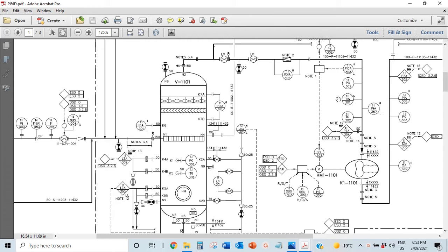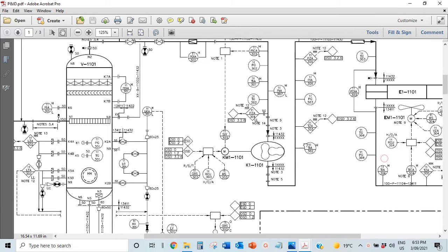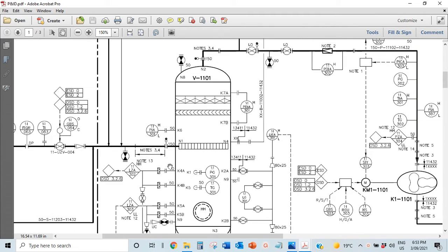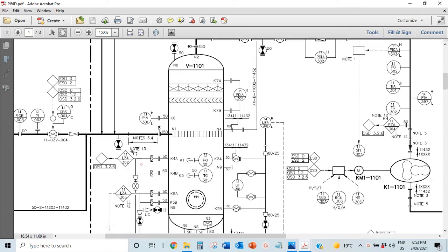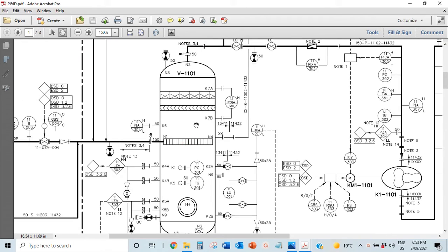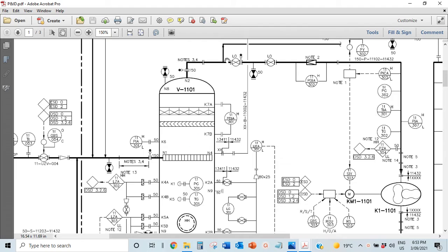So this is the kind of system you would use to do that. You would need a compressor and some fans. The gas comes in from here, and it's going to be mainly gas, though it could have liquids in it. It comes in here, the liquid goes to the bottom, and the gas goes out the top.